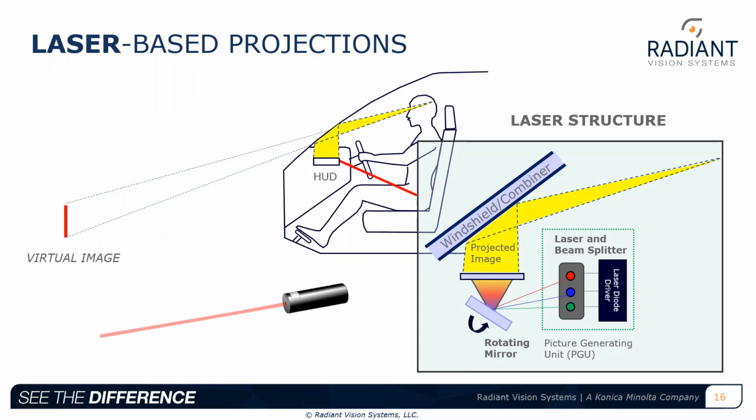I mentioned before that there are three primary types of technologies that make up head-up displays: lasers, TFTs, and DLPs. Laser-based technology uses a laser diode system from a PGU, which uses a single beam projection. The laser beam shoots onto a micromirror plate, which reflects and steers the beam to a translucent film attached to the windshield, which then distributes the image out at a fixed distance. Generally, as with traditional and conventional HUDs, that is somewhere between 2 and 4 meters.